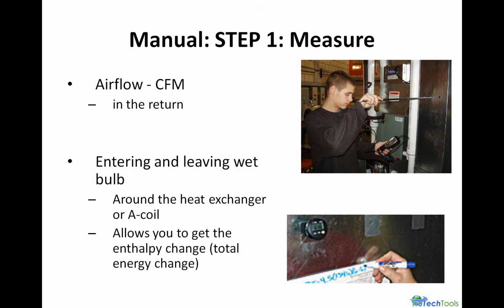If you're going to use a Pitot tube or a hot wire, because maybe you already own one of those instruments, you need to make sure that you take into account air density and correcting the air density. In other words, getting the pounds mass flow rate across the coil correct. Because not only is there air density playing impact on performance of the equipment, it also affects our airflow measurement. So we've got to make sure that we're taking that into account.